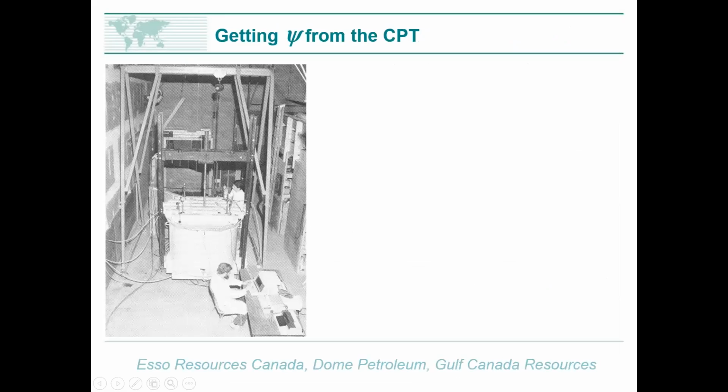Now, we have to then deal with the thing, well, cavity expansion theory, we've got our scaling factor missing. Where are we going to pick our scaling factor up from? The way we do that, and this is us as an industry, this is not particular to the industry in Calgary, what we do is we build giant triaxial tests and we push the CPT into it. So what you're looking at here, this is actually in Calgary. This is the old Golder lab in Calgary, I think on Farrell Road, as it was then. And we have a tank, which is about, by memory, 1.4 meters diameter, 1.2 meters high, and sand has been carefully placed into that tank.